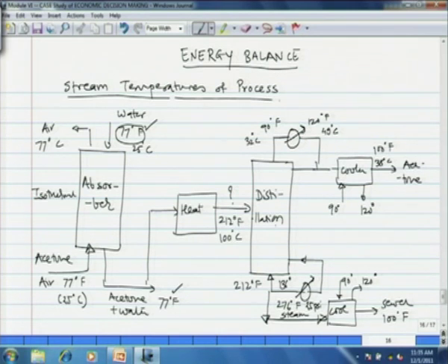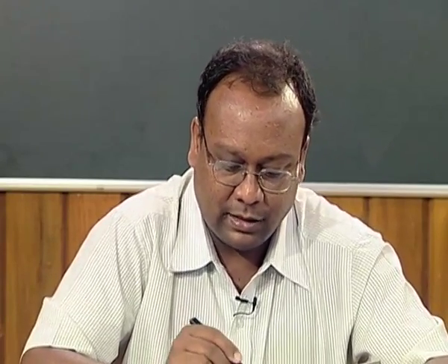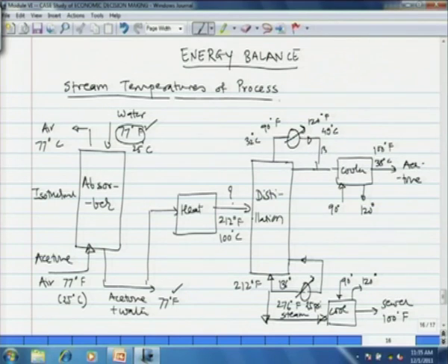degrees centigrade. At the distillation column, we are going to recover pure acetone, 99% acetone at the top as distillate. Once again, the quantity of water in it, as we calculated in the previous module, was very small, only 0.1 mole of water in almost 10.2 moles of acetone. So, the dew point of that particular mixture is going to be very close to the condensation temperature of acetone, and therefore, we assume that the acetone that comes out of the condenser of the distillation column is about 135 degrees Fahrenheit or 57 degrees centigrade, which is the